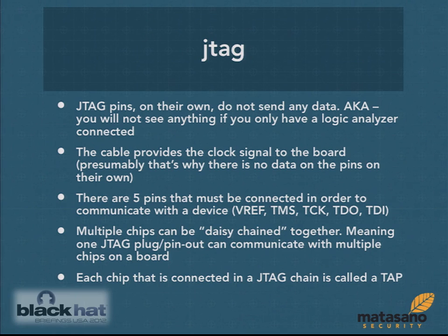Then there are 5 pins that need to be connected: the VREF, TMS, TCK, TDO, and TDI, which I ended up figuring out what they actually meant, but at the time I was looking at pinouts and plugging it in, like, oh, this is TMS, oh, that should be TMS. But there are 14 pins on these pads, so my problem was, how do I know which 5 pins I should be plugging in?